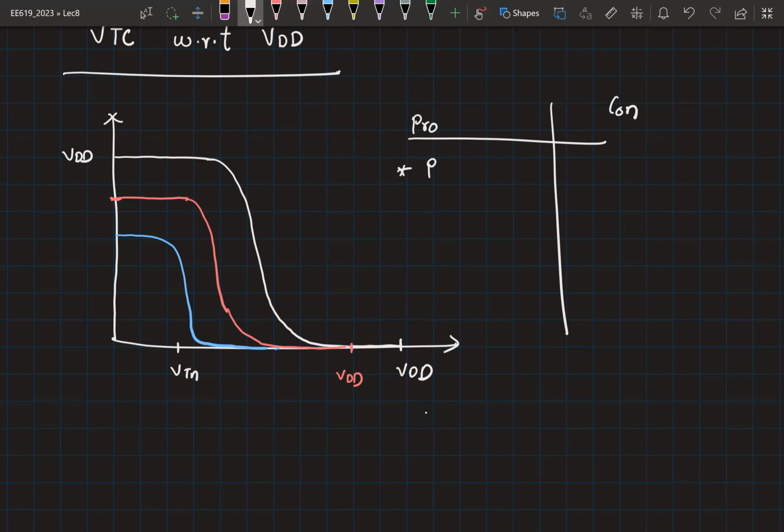You're right. So your power is going to reduce because the VDD is reducing. Power consumption is calculated as VDD times some current. VDD is reducing. Now, when VDD reduces, your VOH is also reducing, which means the voltage applied at the gate of the inverter is reducing. So the gate to source voltage is reducing, which means the current that is being consumed will also reduce. So you have a double benefit. So your power consumption is reducing. The other part is that the gain of these regions, the slope of the transition regions, is actually improving. So the gain is improving.